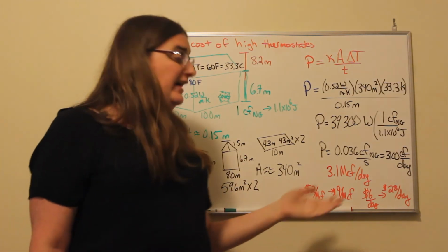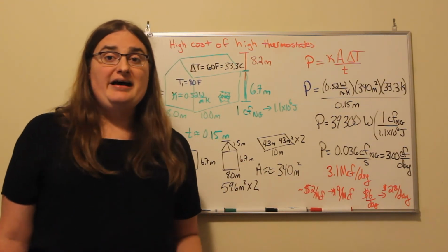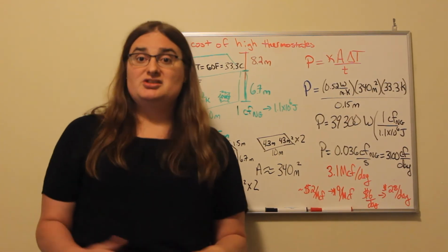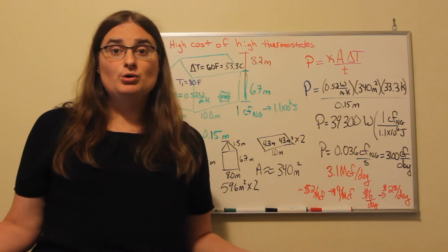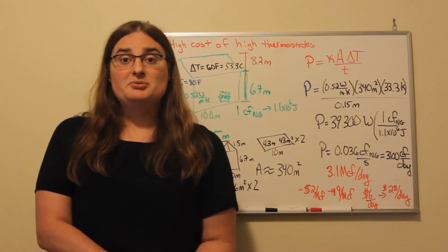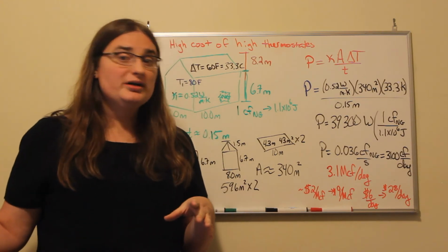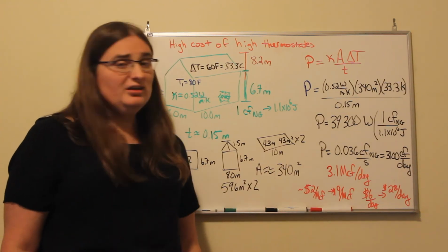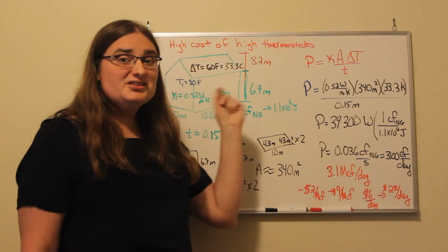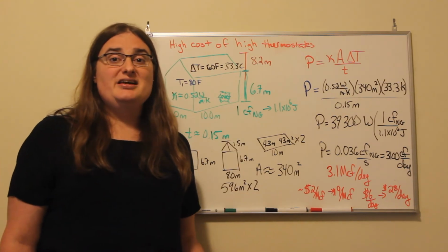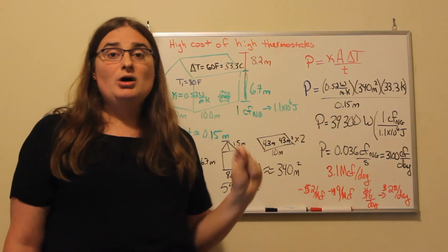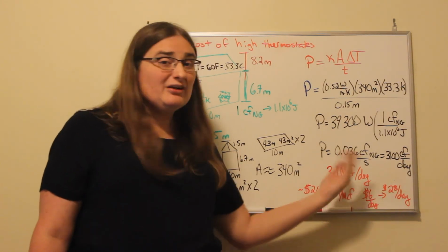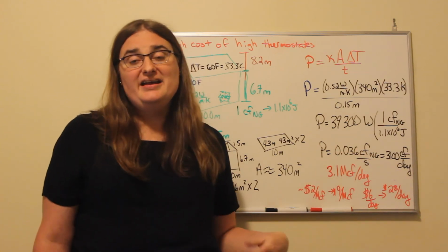Now, taking a look at utility rates in Ohio right now, some rates are lower than $2 per 1,000 cubic feet because there's a pretty big energy price war going on in the midst of the economic slowdown of early 2020. It can be as high as $9 per 1,000 cubic feet. So that means that if it's about 20 Fahrenheit outside, a pretty cold winter's day, you have thin walls and you want to keep the thermostat set at 80, it's costing you between $6 and about $28 to $30 a day to heat your house.